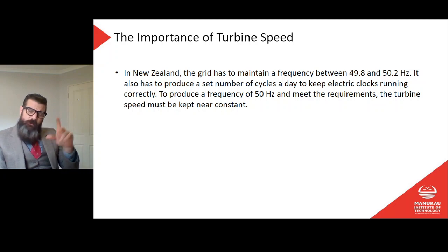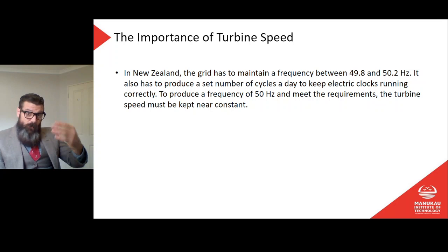When we talked about generators in the last topic, I talked about governors and voltage regulators and how that relationship works, where the voltage regulator is telling the governor to put more fuel in or take fuel out. As the load changes, it's sensing the change in speed, and what it's trying to do is keep the engine speed precisely the same. And as we alter the load, we have to change the fuel input into the engine to keep that speed the same.